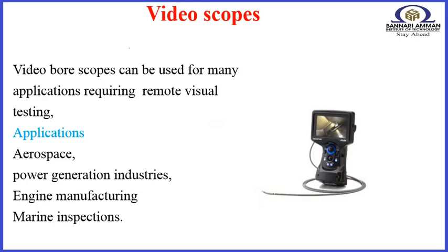Critical visual inspection of hollow helicopter blades is carried out using video borescopes, as well as the inner surfaces of jet engines and wings. The chemical industry makes wide use of visual inspection to test furnaces, combustion chambers, heat exchangers, pressure vessels, and numerous other areas within the plant. In the automotive industry, the internal condition of engines can be assessed, such as carbon deposits on valves, broken transmission gear teeth and gear wear being very easy to find.